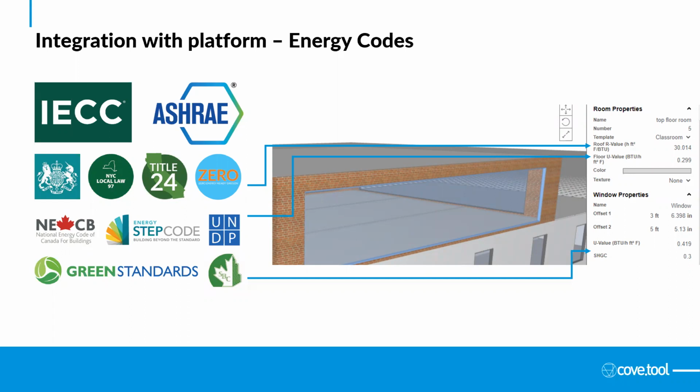And of course, the goal of this, and really the intention, is to customize these. So say I know I'm going to do a better roof. I know on my south facade I'm going to do better glass because I know I'll have more heat gain there. So you can make all those adjustments and send those into the tool, so you can get the exact detail loads that you'll need to have.